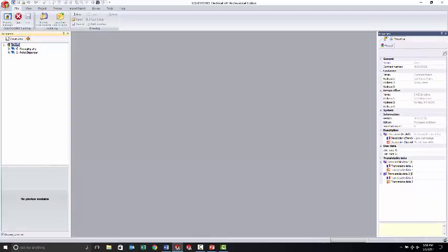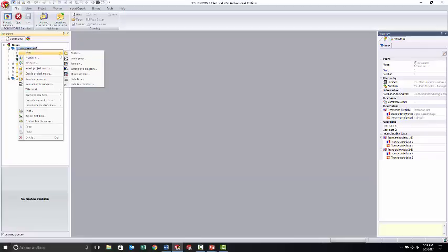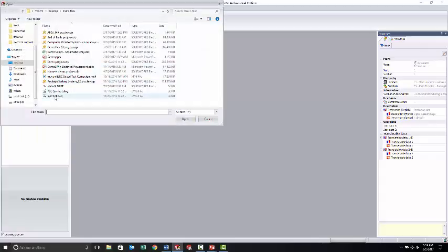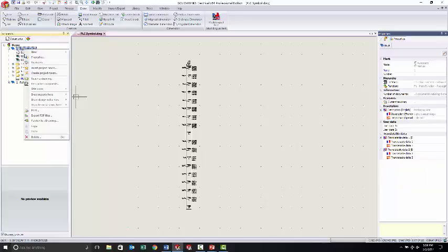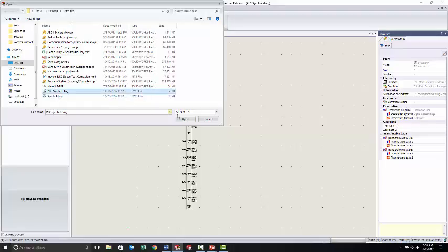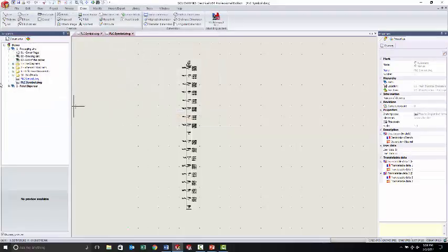So when you're in the document tree here, you can create new things in your book by just going to File, New. And here you'll notice under Data Files, we have Data Files and Data Shortcuts. The data file is going to grab a specific piece and actually put it in the drawing set so that it is now part of the drawing set, a separate entity, it's a copy of. However, when you do it the other way here with the new shortcut, what that is going to do is just create that hyperlink. You can see the difference is just that it's creating this hyperlink here.